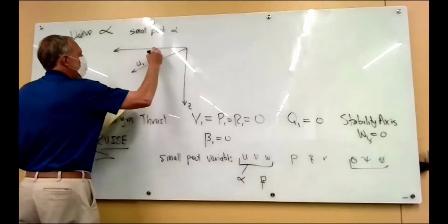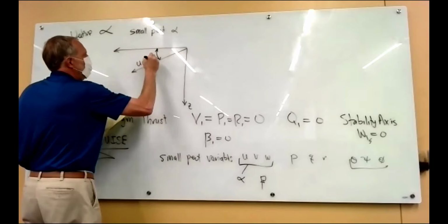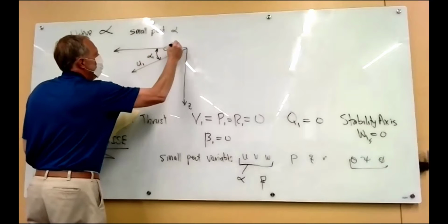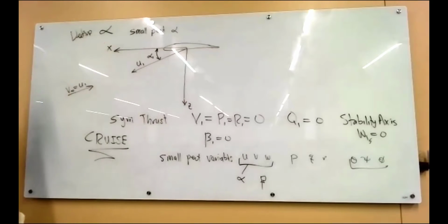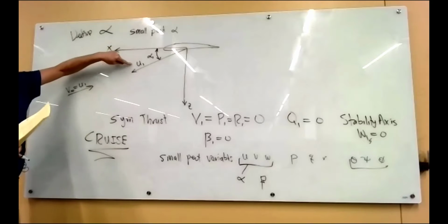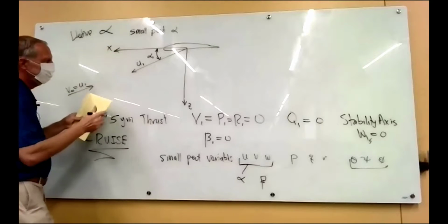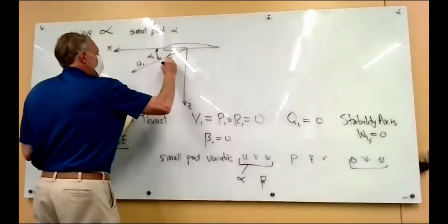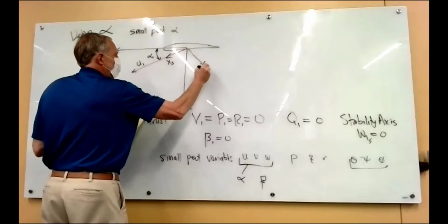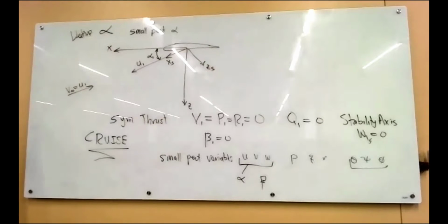And in fact, this is the angle of attack of the airplane, right? Because here's the wing. I mean, we could imagine the wing being lined up with the x-axis here. And the wind's coming up. And again, there's no W. You maybe would think there'd be a W vector, but we're in the XS, ZS axis, and in fact, draw those in here. So put a little version here, put an XS here, and a ZS here. So in stability axis, all we have is U1.